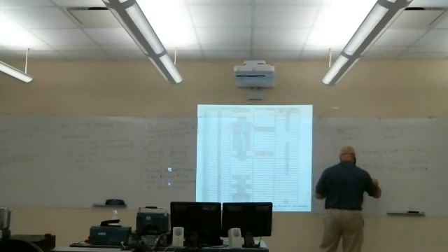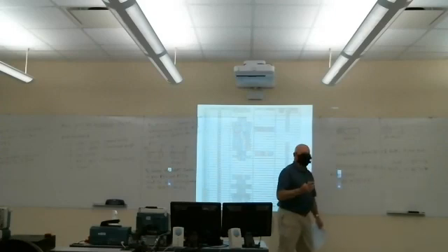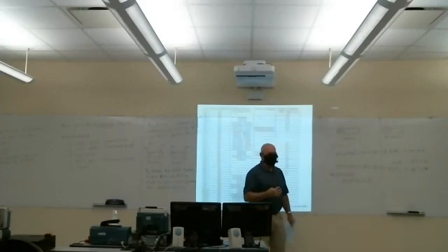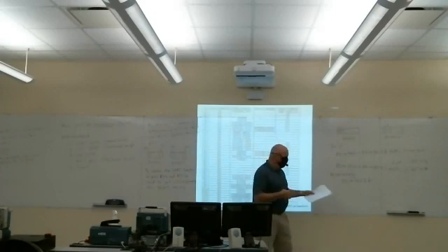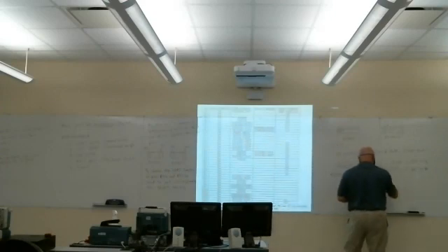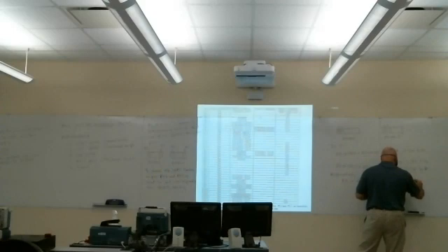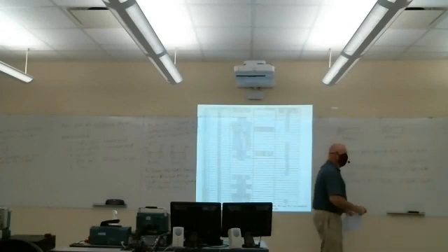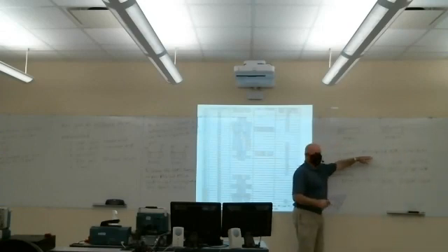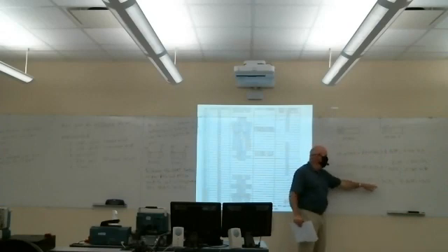You can do it like this, and equal, it's that compound operation, but it means read the value and AND this value with, now here, I'm going to do the complement of 0xC0, because 0x3F is the bit complement of 0xC0. Now, why do it that way? It's exactly the same as the line above. This saves me some typing. This is shorthand notation for equal and.